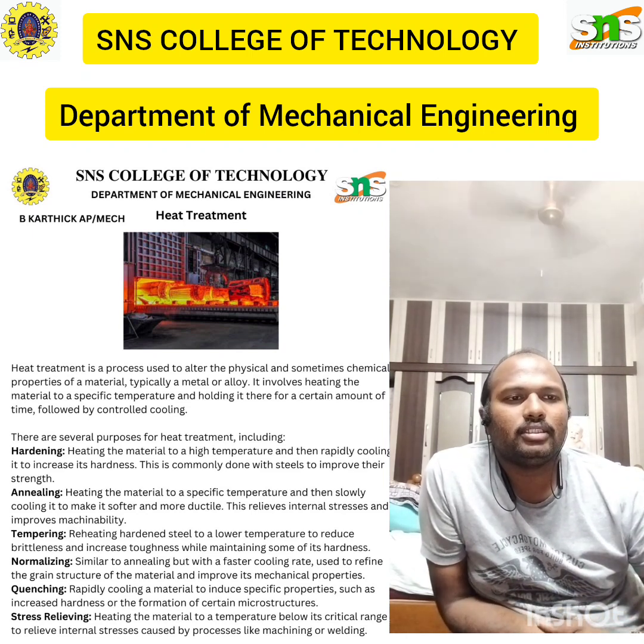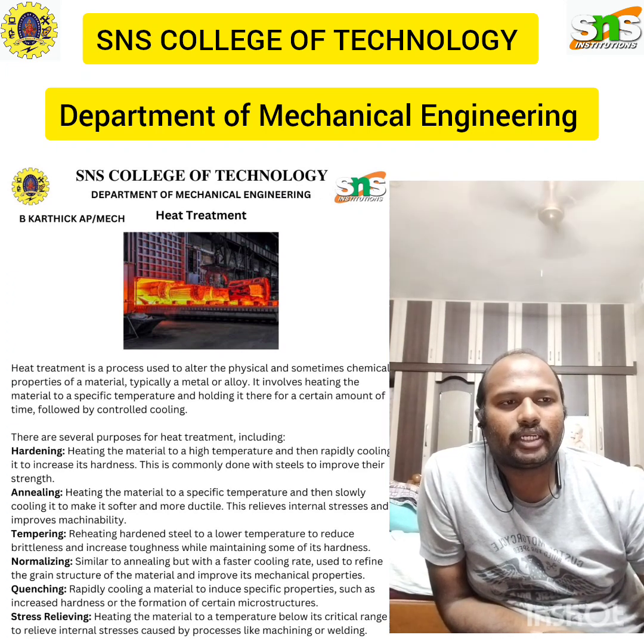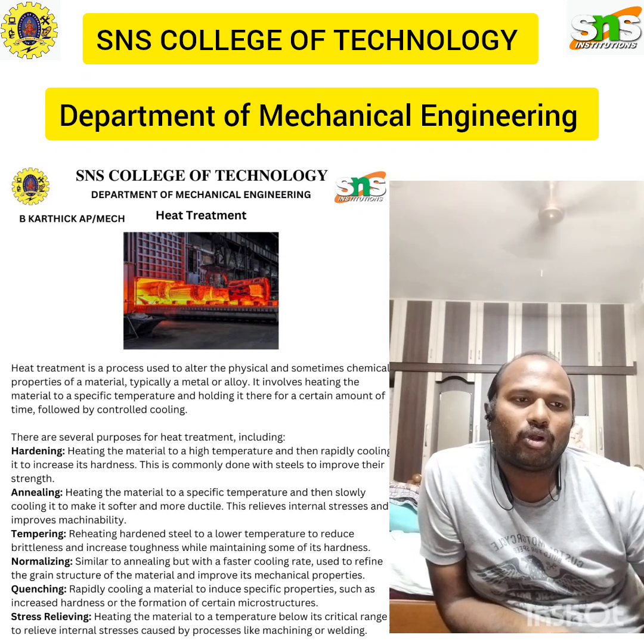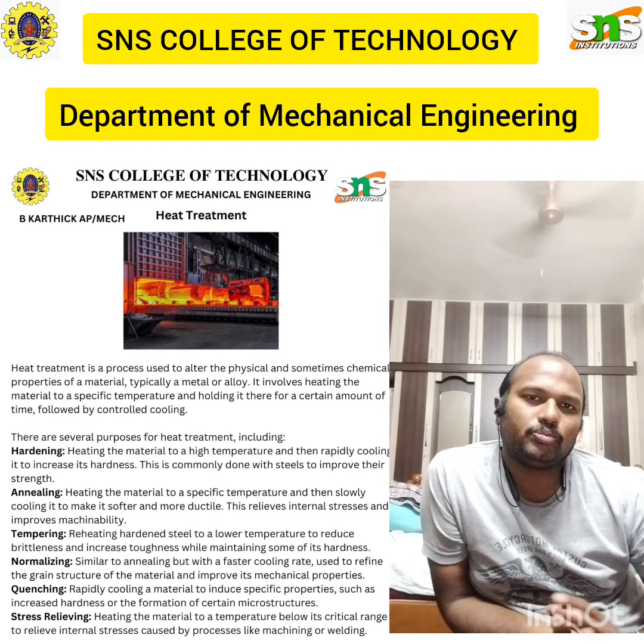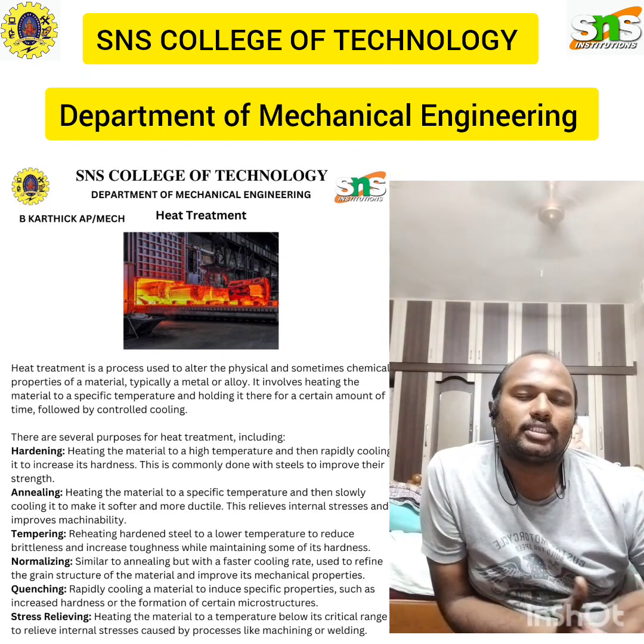Coming back to normalizing, heating to a specific temperature and cooling it in air refines the grain structure and improves the mechanical properties. The last one is quenching, rapidly cooling the material in a quenching medium such as oil or water to achieve specific properties like hardness and strength.